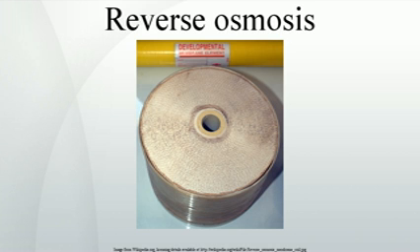Reverse osmosis is extensively used in the dairy industry for the production of whey protein powders and for the concentration of milk to reduce shipping costs. In whey applications, the whey, liquid remaining after cheese manufacture, is concentrated with reverse osmosis from 6% total solids to 10 to 20% total solids before ultrafiltration processing. The ultrafiltration retentate can then be used to make various whey powders, including whey protein isolate.